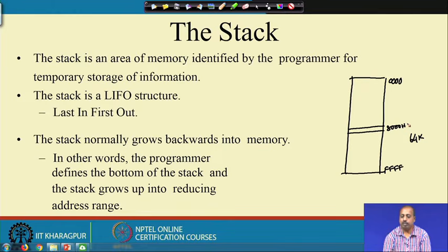Normally the stack starts growing from this point towards the 0 side. Of course, that is the convention only, but the way stack manipulations have been implemented in the 8085 processor, it grows backwards towards lower and lower addresses. As a programmer you can define the bottom of the stack, and from that point onwards it grows by reducing the address value.